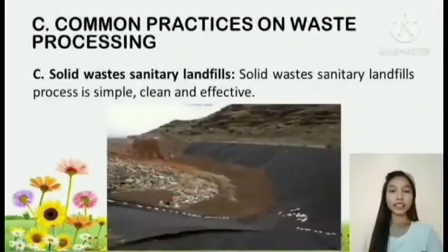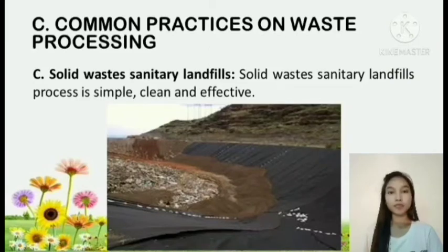C. Solid waste sanitary landfills. The solid waste sanitary landfill process is simple, clean, and effective. In this procedure, layers are compressed with some mechanical equipment and covered with earth, leveled and compacted. The main purpose of a sanitary landfill is to ensure waste is safe by reducing the harm from accumulated waste and allowing safe decomposition. Besides, it involves well-designed engineering methods to protect the environment from contamination by solid or liquid waste.